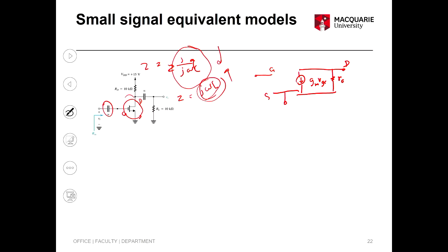Okay, so that's a trick that we use. If we want to separate DC from AC, you can use caps. For DC, it's an open circuit. For AC, this is a short circuit. And that's why in the small signal model, when you draw the equivalent circuit model, you replace these caps by a short. I guess you remember that from the previous courses. But if not, all the caps for higher frequency AC signals, we can short them. So now that means your V1 has no cap, it's shorted.